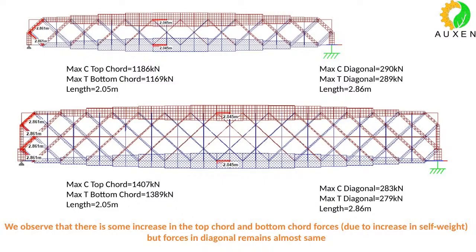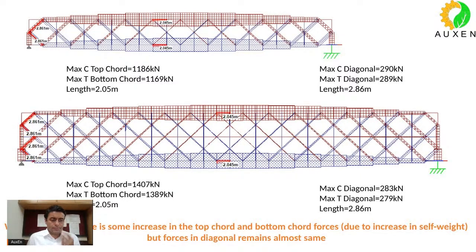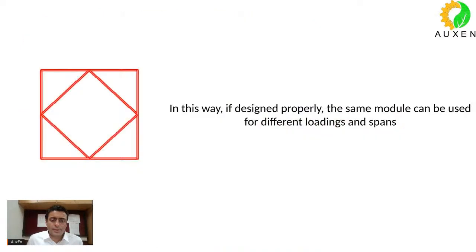Another important point that you should understand over here is the ease of connections. So if you have this type of a Bailey system, it becomes very easy to connect all these diagonals together. Why? Because all these compression tensions in the diagonals will be counter balancing each other, making our connections very light. Okay, so even our connections become quite light where diagonals are getting connected, and this entire system is an excellent system to be repeated and to be used for different loadings for different configurations.